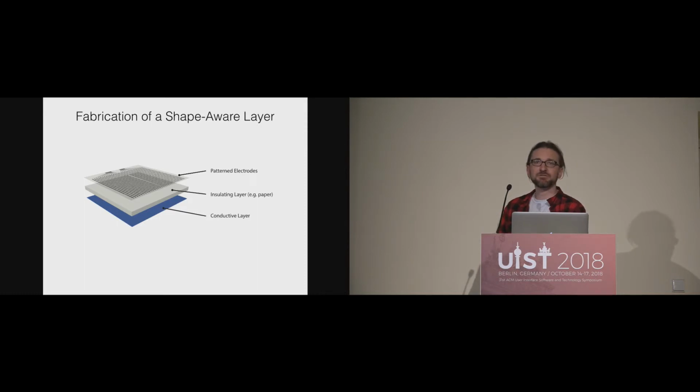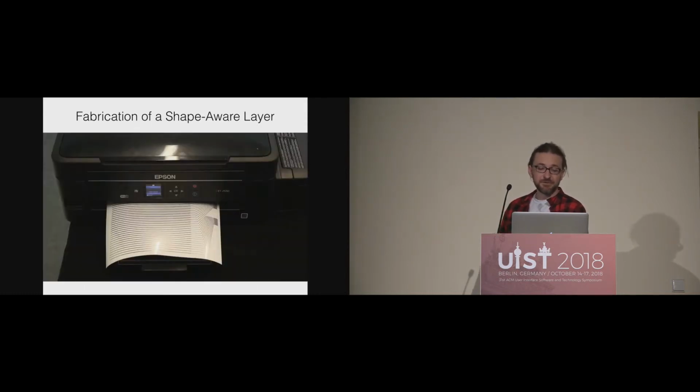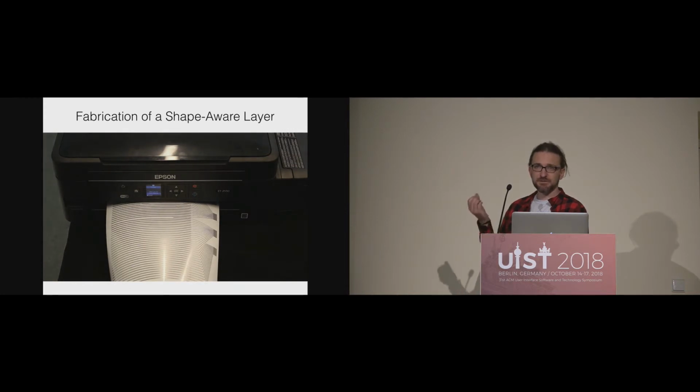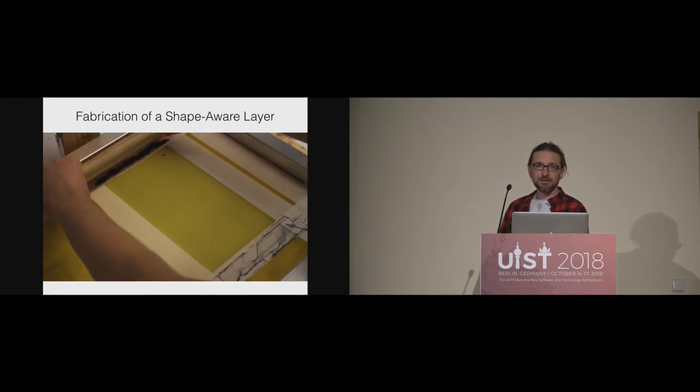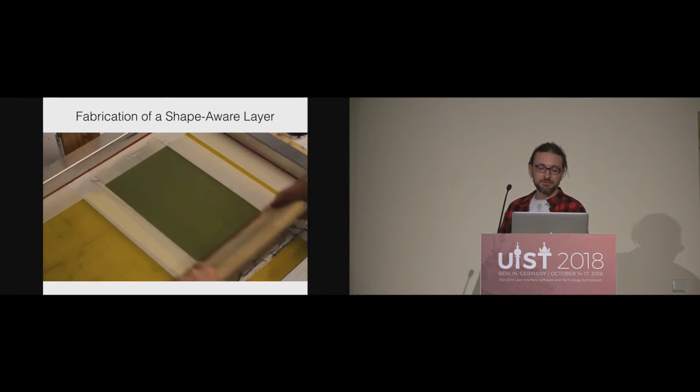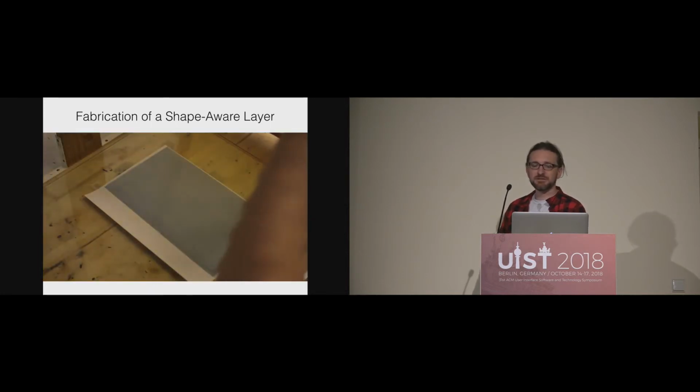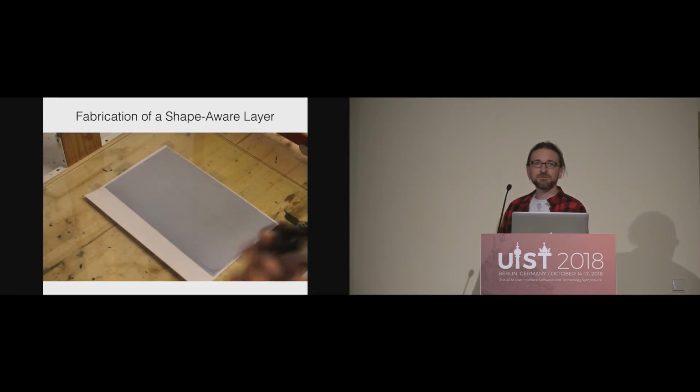The fabrication of each of these layers. For this, we use an inexpensive and rapid fabrication technology based on inkjet printing that prints conductive silver traces. This technology is also commercially available. With this one, we print the top layer with all the detailed sensors. And for the back electrode, at the moment, we use screen printing of a conductive polymer called PEDOT:PSS. But alternative solutions are possible.